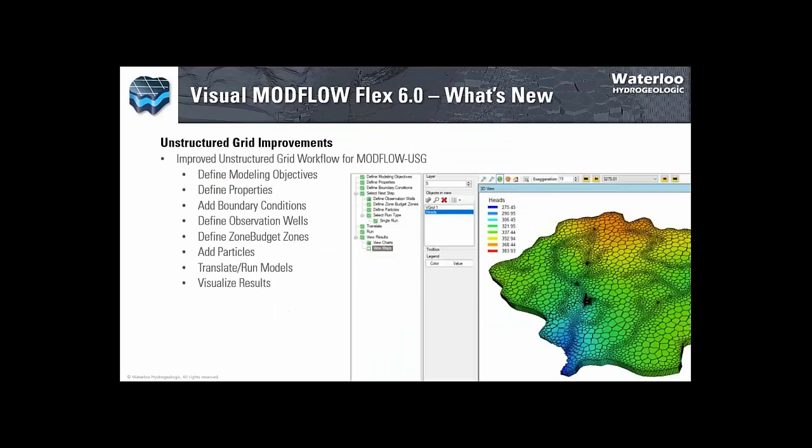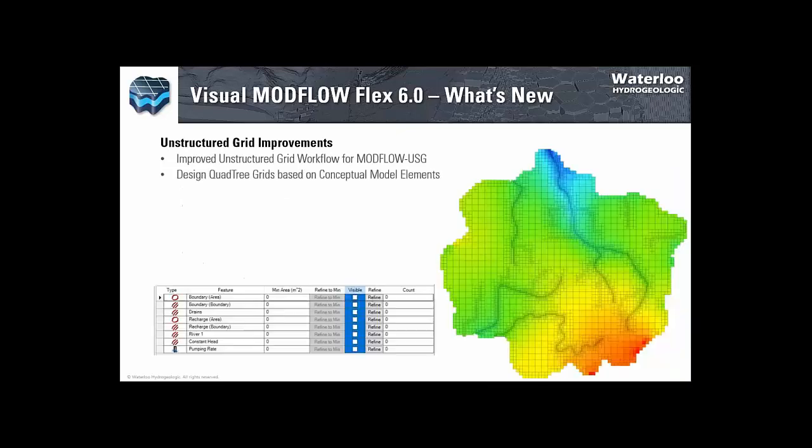The main new features that we've introduced in version 6 are significantly around unstructured grids and improving the functionality for those. So the first thing that we've done is introduced a full workflow for working with unstructured grids that has all of the steps that you're used to when working with finite difference grids. There's the defined modeling objectives, defining properties, boundary conditions, and new is defining observation wells, zone budget zones, and the addition of particles for particle tracking. You can also now build Quadtree grids, and we'll go over that in the demo.